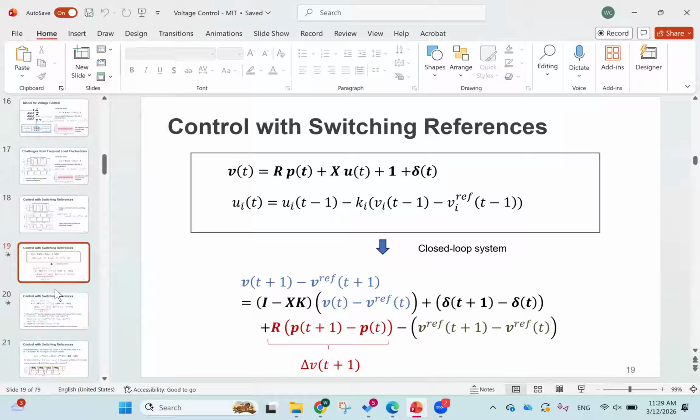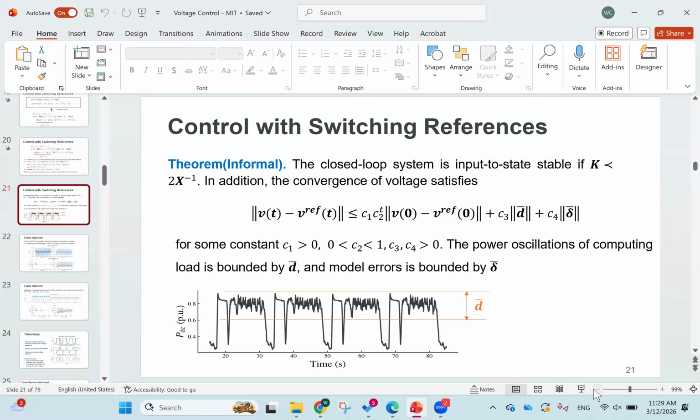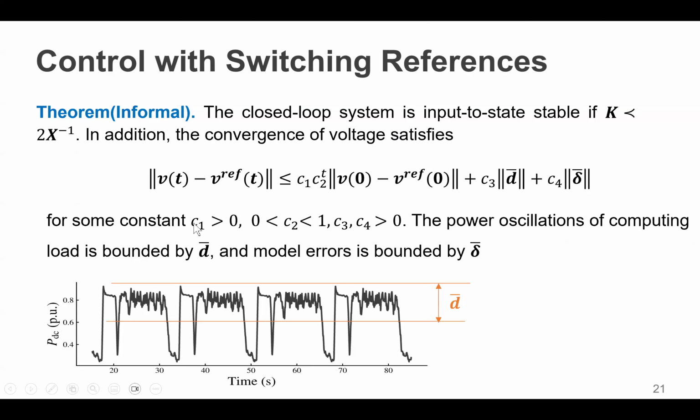So I think perhaps this slide can be helpful. So for the real world, the data center load is kind of this way, right? Then the time oscillation may be about 10 milliseconds. That is this power profile. What we are doing is that we implement 1 control action every 1 second, so that is 1 action here, 1 action here, 1 action here, something like that. So there will still be the oscillation of the load in between. But as long as we are reacting to the largest changes of the power, we can still keep the voltage.